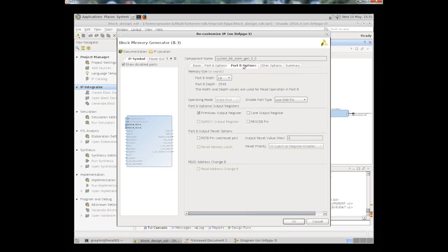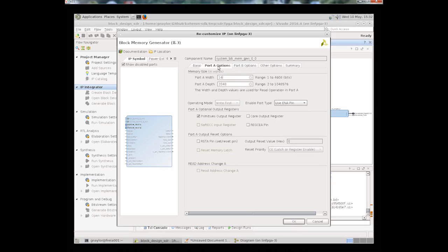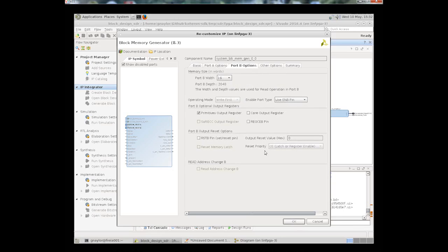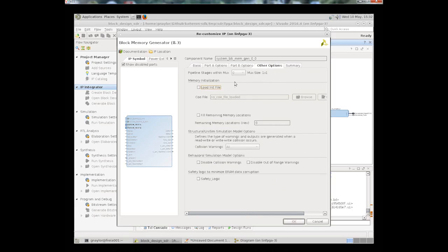And we're going to use port B to send out the quadrature version of the local oscillator. So port A will be the in phase, port B will be the out of phase local oscillator. So what we're doing now is building a DDS, a digital synthesizer. So the thing is to define the contents.